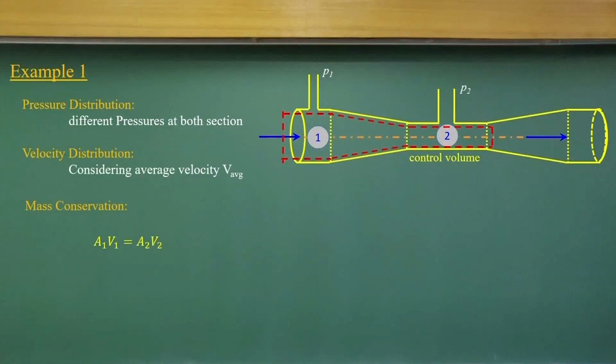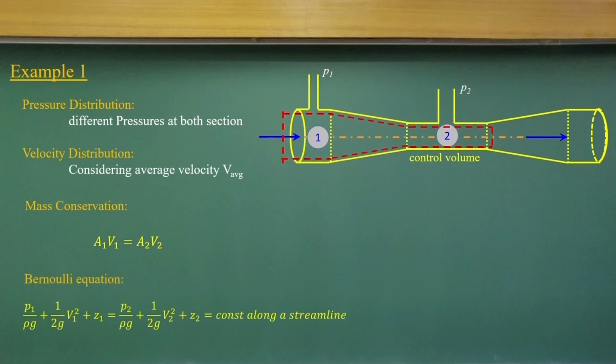in terms of average velocities. So, we are not considering turbulent or laminar velocity profiles, and we are not putting in any kinetic energy correction factors, which are supposed to be used, but in this case we have not done it. We just apply the mass conservation and the Bernoulli's equations, assuming that there is a uniform flow distribution. It does not happen like that.